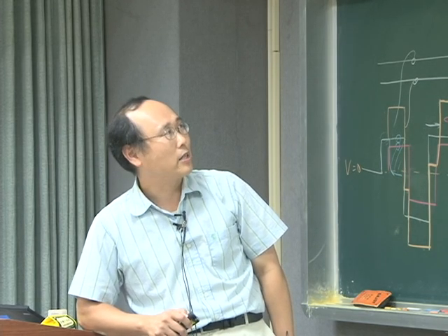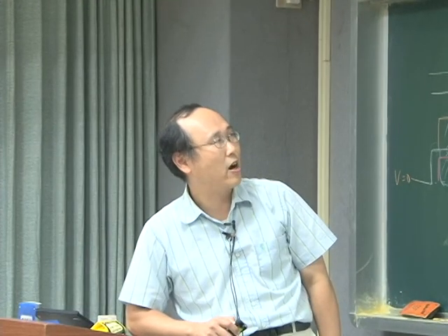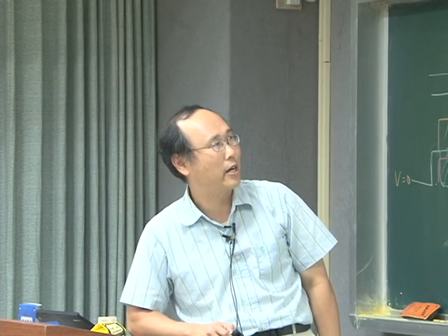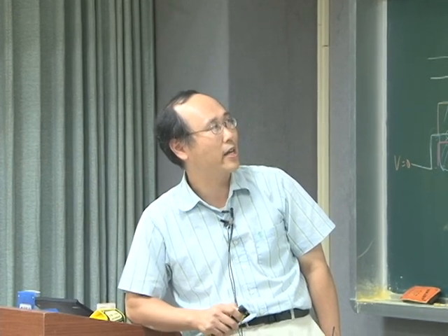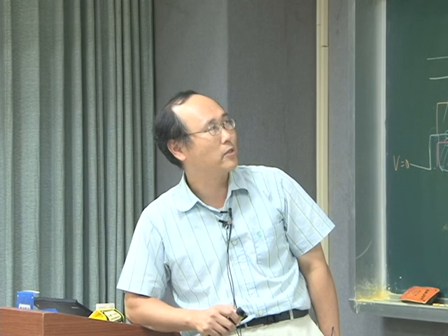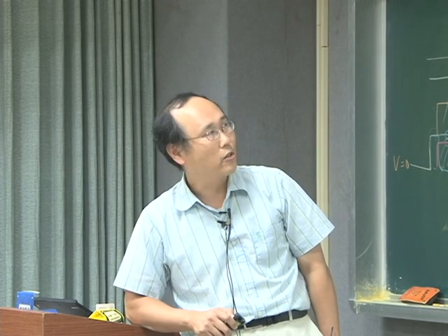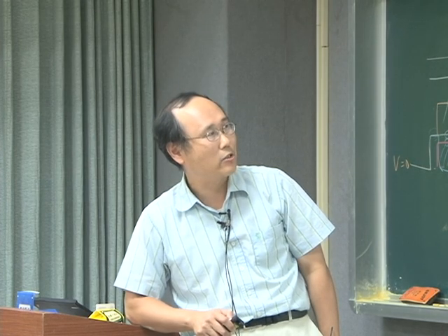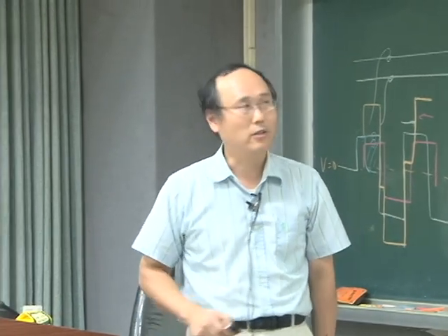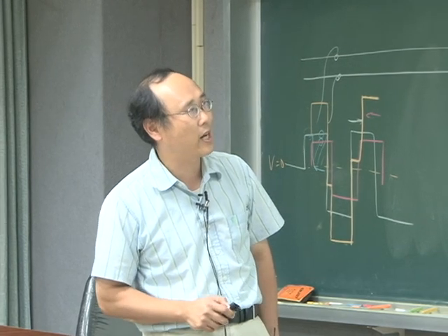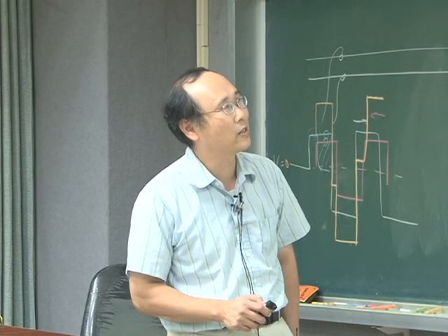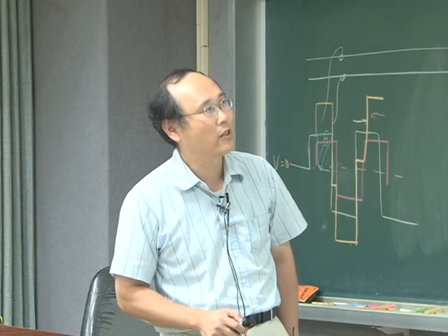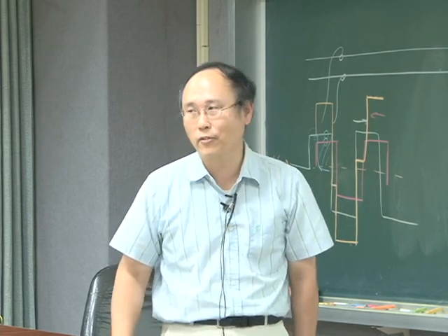Okay. Suppose this is a time harmonic field, so you can use a cosine plus some arbitrary phase to represent this voltage and also to represent this current. So if we put these two together and use some trigonometry formula, you end up having this result. All right, multiplication of 2 cosine gives you the summation of 2 cosine. And the argument for this one is the subtraction of the phase. And the argument for this one is the addition of the phase.